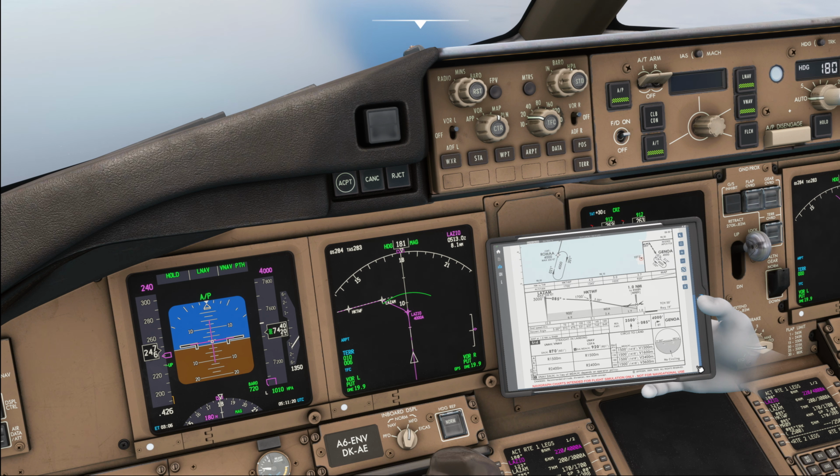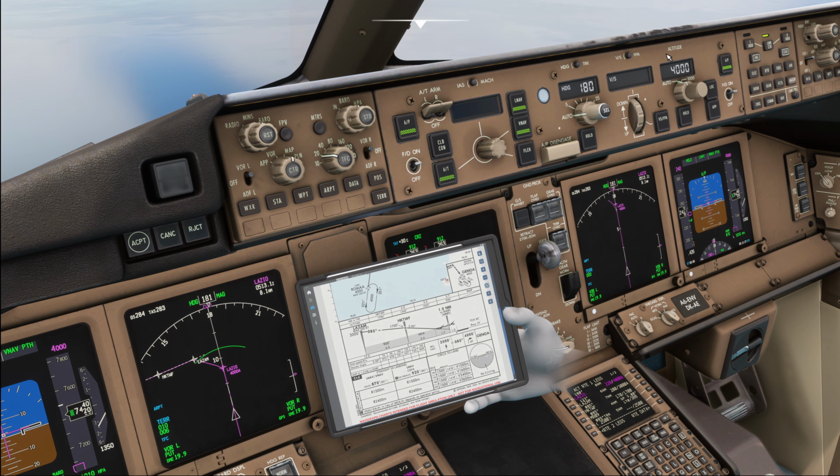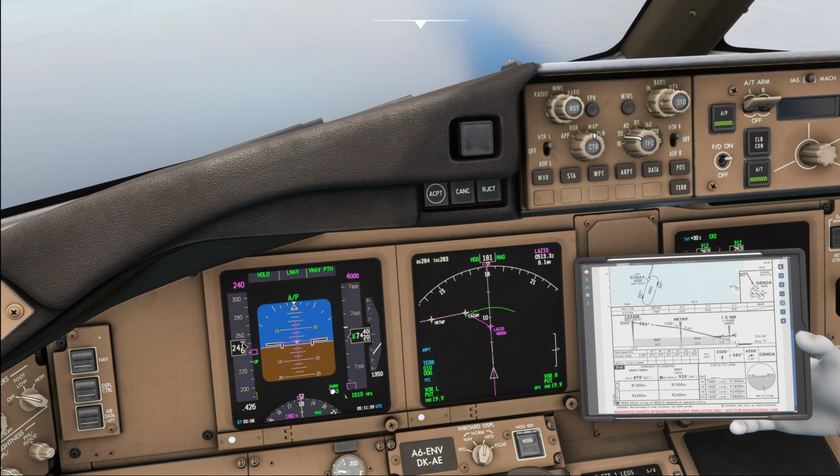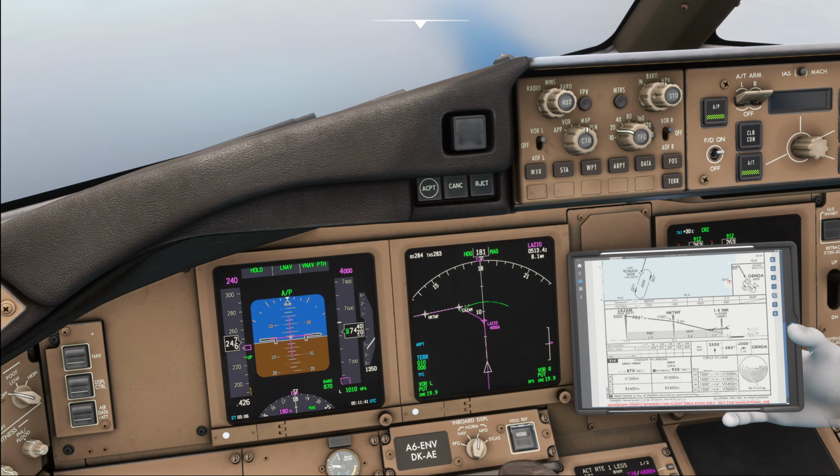And setting the minimum is quite important. The 777's autoflight system has a dedicated feature that allows you to set the exact minimum altitude on the MCP if auto mode is selected down here. So if you're in thousands you can't do it. In auto you can set it right down to the very exact minimum. So it is important that the minimum is correctly set down here.